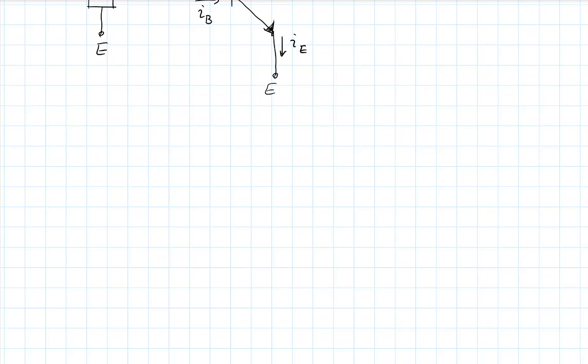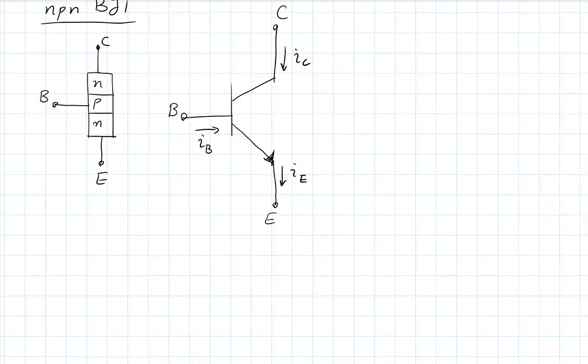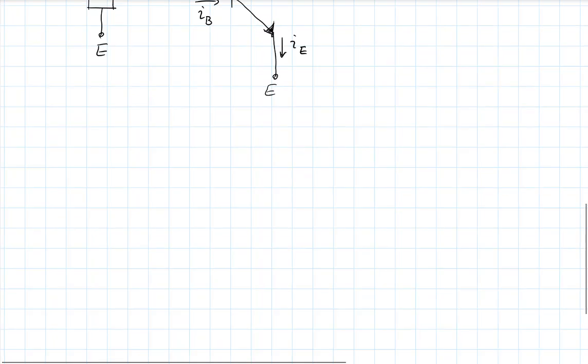You can formally think of, in fact, 3 regions of operation for this device. We talked about active and saturation modes, and we'll repeat them in a moment. But there's also this thing called cutoff, when it's off, and it's not doing anything. So it's not very exciting. And that's when your base emitter voltage is so low that that diode is not even on. So there is no current going there. Okay? So let's write these down.